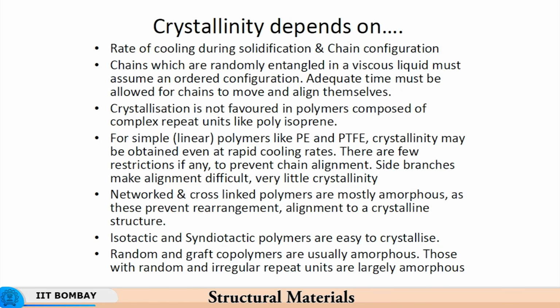Isotactic and syndiotactic polymers are easy to crystallize. Now, crystallization or any ordered arrangement of atoms requires some symmetry, some ordered arrangement of atoms in the polymeric chains themselves. So if you have isotactic or syndiotactic arrangement of polymer chains, then you will have symmetry in the arrangement of the functional groups, as a result of which the alignment of these functional groups in the two chains will become easier because of the symmetry that is present, and then they will be easier